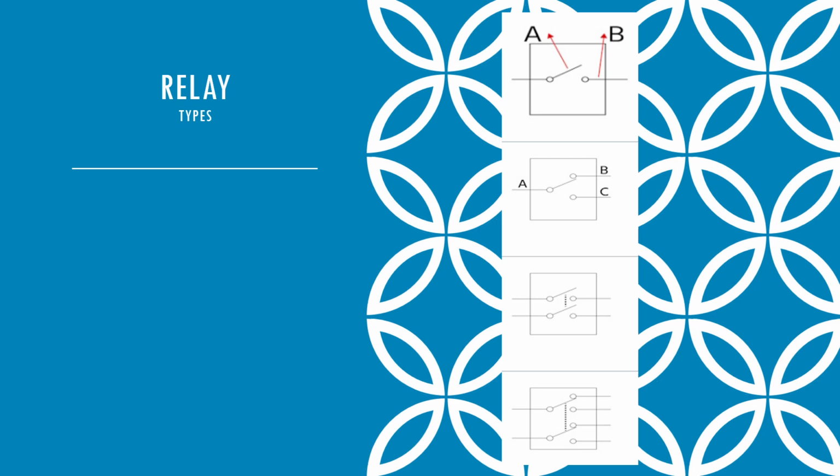Different types of relays. So up here at the top, you just have your basic on and off. This is called single pole, single throw. The pole is how many circuits you can control. The throw is how many outputs you have. Here there's just one choice. They do, however, come in a normally open or normally closed position, and that can help out with safety.